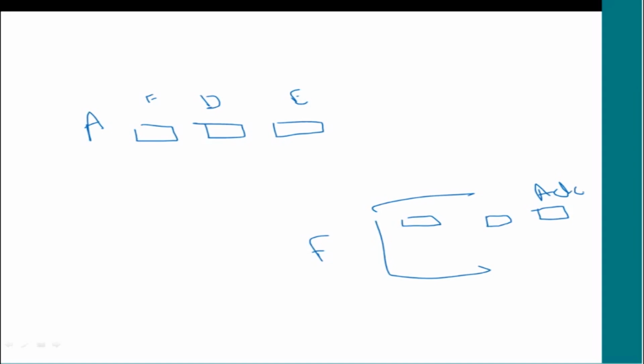Now the add instruction is here. Mull also has been read by the coprocessor. The floating point coprocessor has already read the mull instruction, but it cannot execute it. Typically these two instructions are to be handled by this processor only, but it is already executing the add in its own pipeline, so it cannot execute this instruction now. This instruction has to wait.